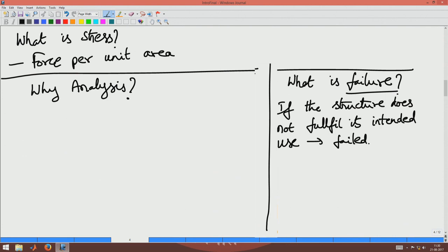I will give you some examples. In buildings, you have a reinforced concrete beam which would have cracked due to the dead load. That is not a failure of the beam. The same reinforced concrete beam, if it were to be part of a water tank, the cracking of the beam is detrimental because water will seep in through the cracks, deteriorate the concrete, and it might also cause leakage of water stored in the tank.